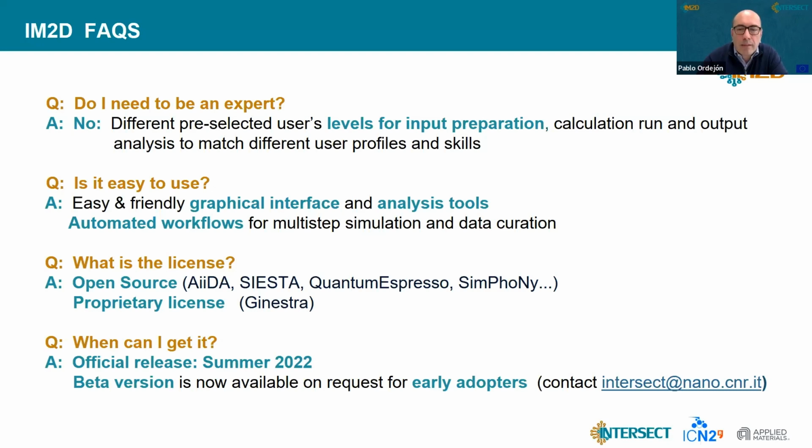Right. So this is something that the DFT community has done for a long time already, but those were very, very involved calculations. One of these calculations would almost be a PhD thesis of a student. But right now you have the workflows to compute, for instance, the charge states of a defect and compare the energies and the stability, and in which situations a defect will be charged or not, what will be the energy for charging or trapping charges or carriers in that state, and that's a key parameter to determine the performance of the device.